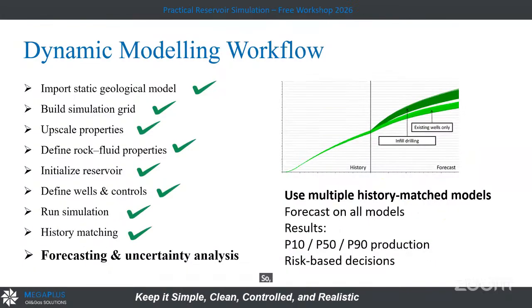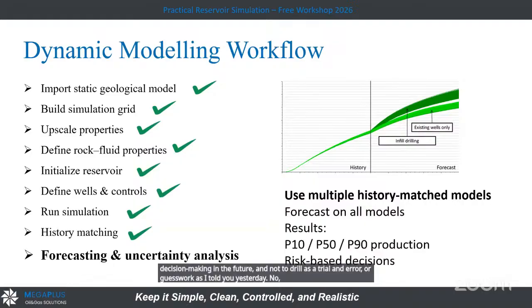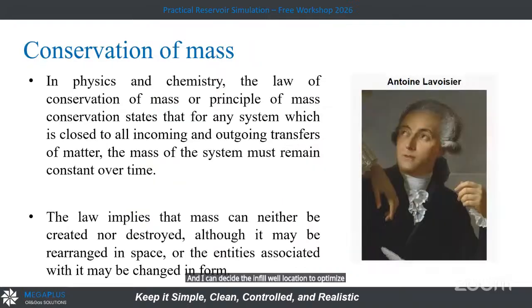After that, as I mentioned, I will do my forecast, adding my infill wells, and I have a model that is useful. It's not 100% right, but it's useful. I can depend on it in decision making in the future, and not drill as trial and error or guesswork, as I told you yesterday. It's a model that I made, and I have a history match, and I can decide the infill well location to optimize the production from the field.